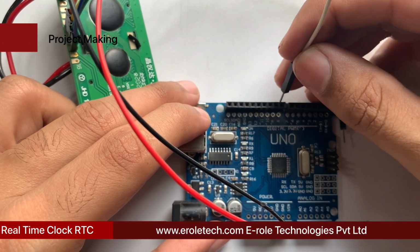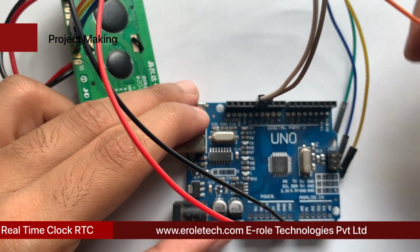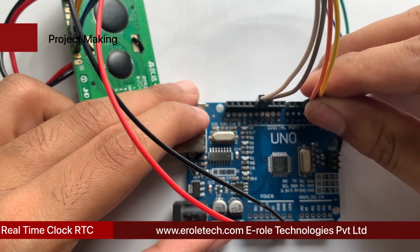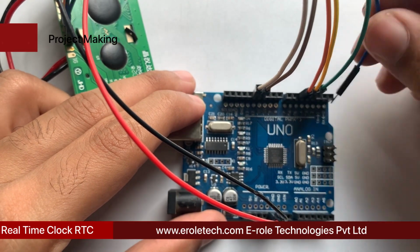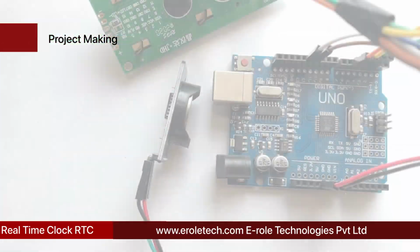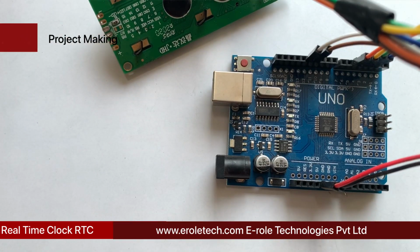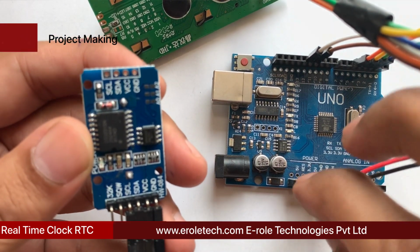Now connect white, brown, orange, yellow, green, and blue wires with pin number 12, 11, 5, 4, 3, and 2 of Arduino respectively. Connect the red wire of the RTC module with 5 volt pin, black wire with the ground pin.